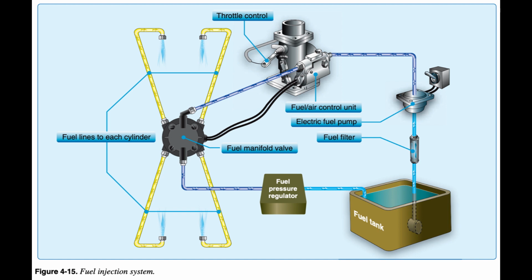Disadvantages include: 1. Difficulty in starting a hot engine. 2. Vapor locks during ground operations on hot days. 3. Problems associated with restarting an engine that quits because of fuel starvation.